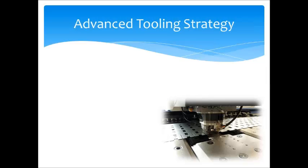What we found in one customer's case is that 65% of their product used exactly the same tools, and they would fit within a 58 station turret. So in tooling strategies, we took a look at the parts and kits that they had to produce, and we found that there was a lot of commonality of tooling.